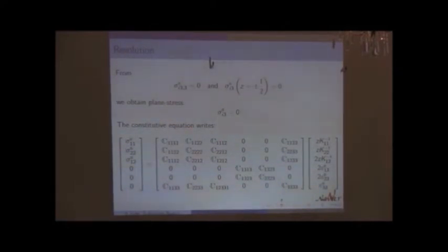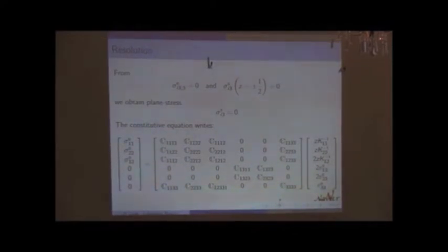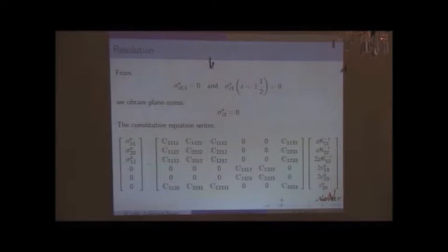This is very intuitive, and actually this is where people who derive Kirchhoff-Love plate theory from an assumption on displacement and the principle of potential energy have difficulties, because they cannot see that it is actually plane stress instead of plane strain.